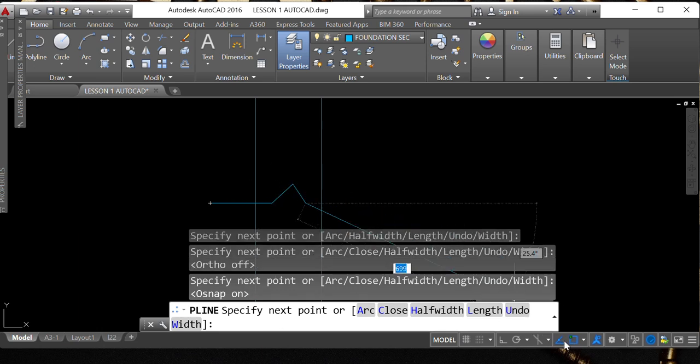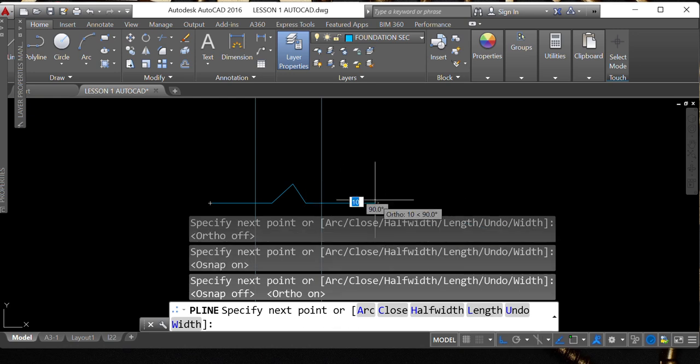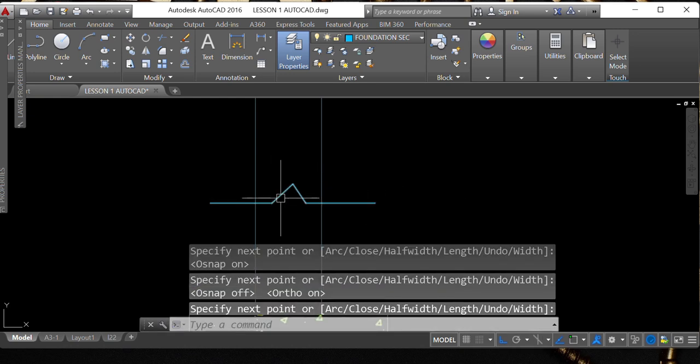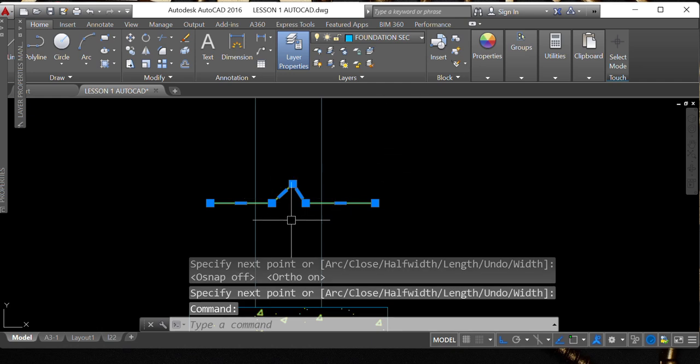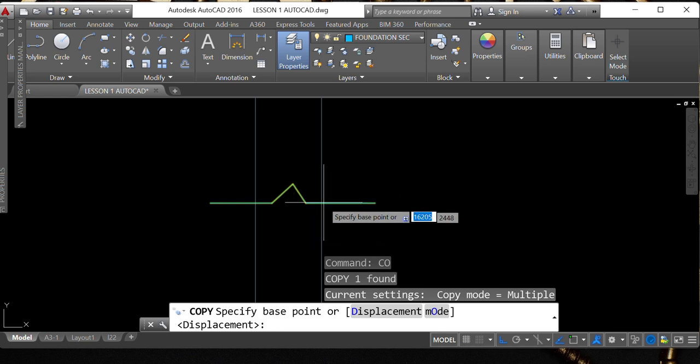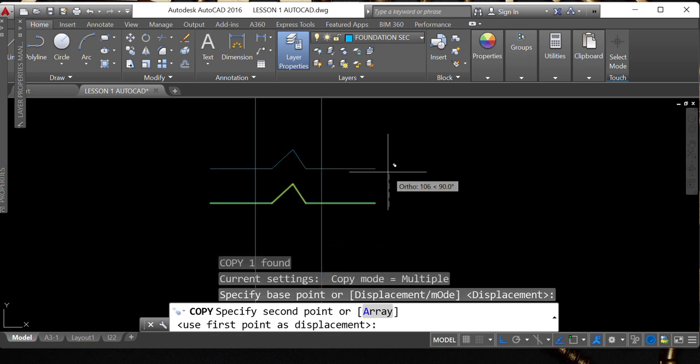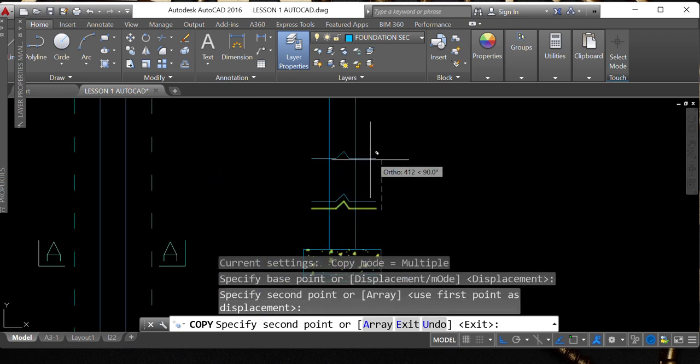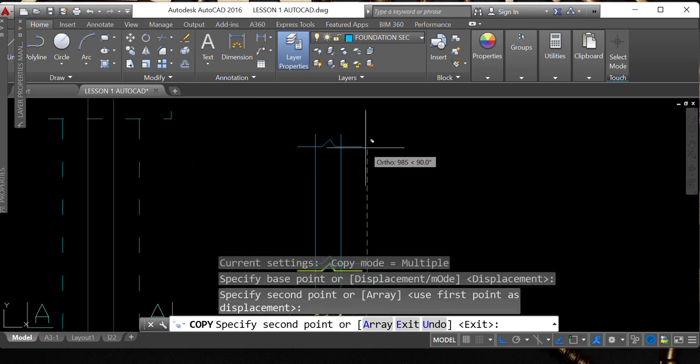Make sure it's horizontal or along the same line as the previous one. I'll finish my line in auto mode, and it's perfectly horizontal. Let's see a polyline there which indicates break, and then I'll copy this. Make the snap mode off. Maybe somewhere there, into the top here.